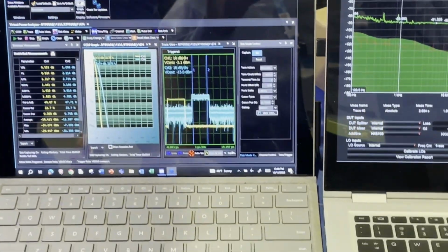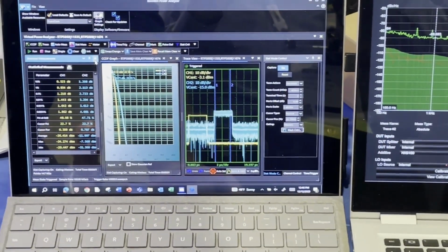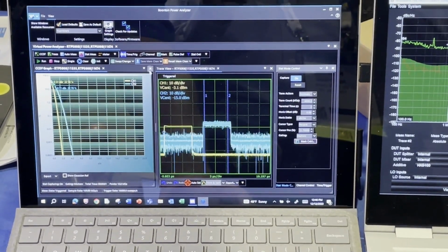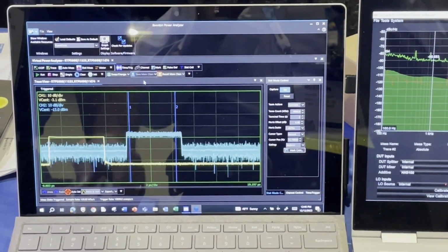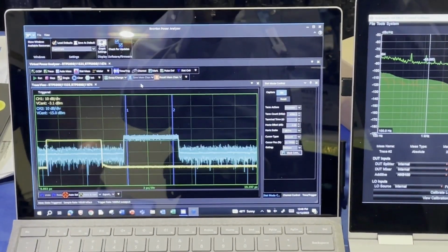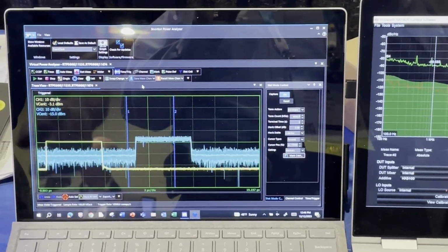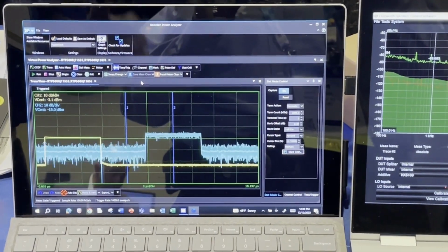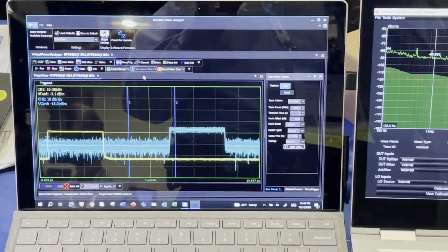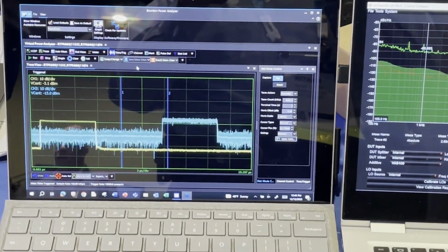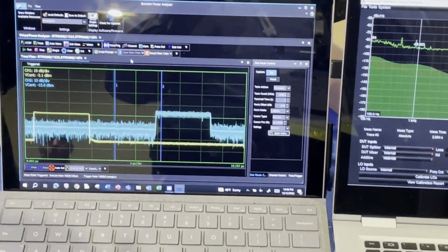Another thing that we can do with that box is timing. And what I'm going to ask Michael to do now is add some latency to the signal. And as we see, as he's adding some delay or latency, we can actually see the input and how much latency we've added. And using our cursor resolution, we can determine the actual delay.